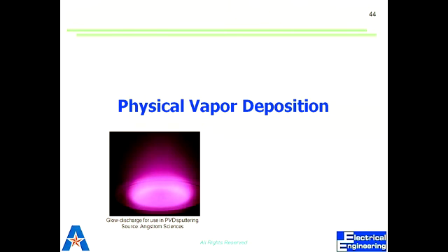What material do you use? Spin on glass is molten glass. You spin it, then you heat it up, and once you heat it up, you take it above the glassification temperature, and then it becomes glass. Before that, it's just a precursor of glass. So probably you need to break down different deposition processes and go with the terminology.